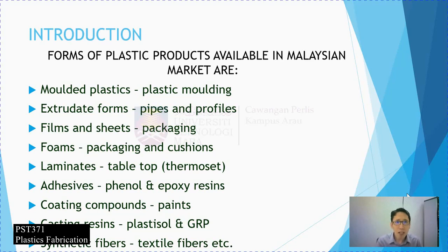For example, some tabletops are made from wood for their aesthetic value. However, wood, as we know, is very fragile toward scratches and mold growth, and it absorbs water significantly. So with thermoset laminates, we protect the wood product so that it can be used as a tabletop and perform well.